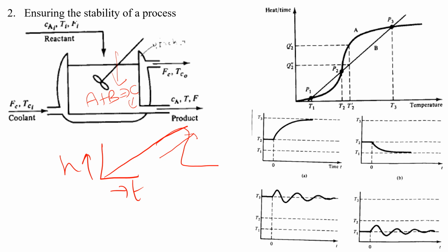So here, this is the dynamics of this system. So this black line says how much heat is evolved at a particular temperature. Actually the straight line is the linear one. This is the expected. So if this system follows this dynamics, then the system is under safety condition, which means stability is maintained. So see the curve. This curve takes this profile and this profile. So if the curve is behind, it means it is stable. If the curve is above this level, it means it is an unstable condition.